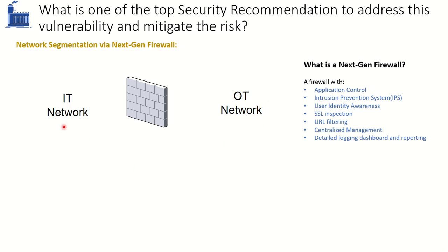In an IT environment, having these endpoint security controls on the IT devices is very common. And plus, the legacy OT devices, these PLCs, do not have built-in intrinsic security features like authentication and everything in place. That is the reason having a segmentation between the IT and the OT network is very important.